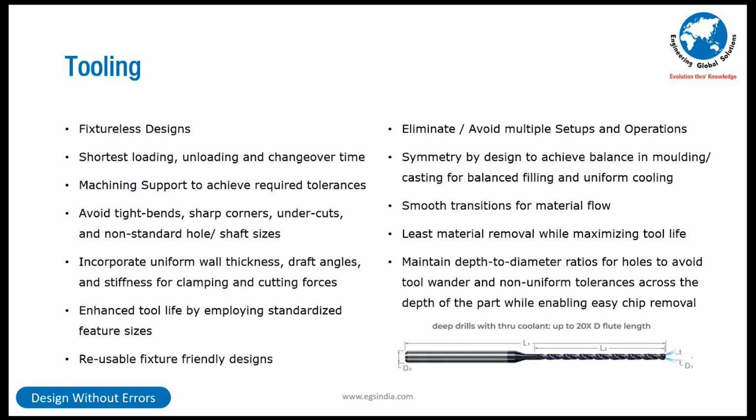Tooling. This is the most important thing because this affects everything else. That's why I've given a very small image and a very large amount of text. Sir, why should I bother about tooling? Some amount of your usage tolerance is going into fixture designs, right? In your locating fixture, manufacturing fixture, your jigs, your inspection fixture, also, certain amount of your 10% of your tolerance is eaten up. So your working tolerance keeps getting shrunk. If it's a fixtureless design, that is the amount that design and manufacturing have.